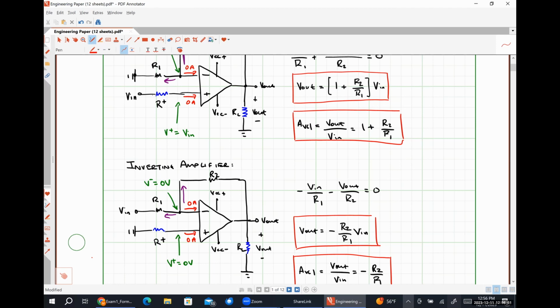Okay. The inverting amplifier, like we see right here, is literally the most commonly used op-amp circuit in the world. It's used in tons of different things, particularly where we don't really care about the polarity of our output voltage. So audio amplifiers and all of that kind of stuff use inverting amplifiers extremely often. Guitar effects pedals use inverting amplifiers for the gain stage. And then they use other components like diodes to give flipping so that you get fuzz pedals and all that kind of jazz. But this guy right here is the meat and potatoes of practically all audio amplification.